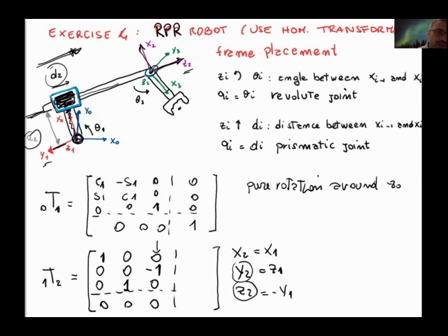First, we move rigidly along the x1 coordinates of how much of h2 as a translation, and we apply then the joint motion along the y1 coordinate. Since the convention is to be positive in this direction, and the y-axis in the other opposite direction, we put a minus d2. And on the z1 axis, we don't have any motion. So this will be the homogeneous transform.